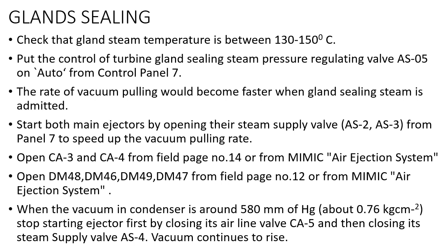So you are withdrawing the starting ejector now and taking the main ejectors in service. So you have to take both the ejectors in service.